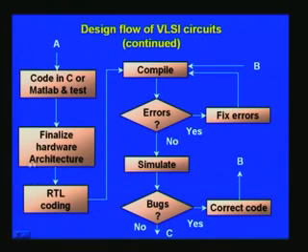So once the architecture is through, you start identifying different blocks and start coding, and it should conform to RTL techniques as such. And next step is you use now the simulator, let us say, or for that matter even in synthesis tool you have a compiler, and so also in the synthesis and simulation tool. And this step is you compile your Verilog code, both the test bench as well as the design as such.